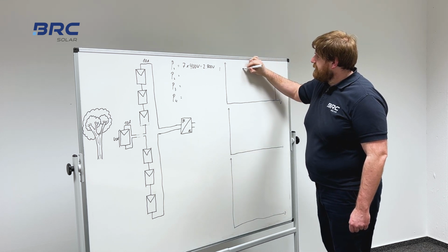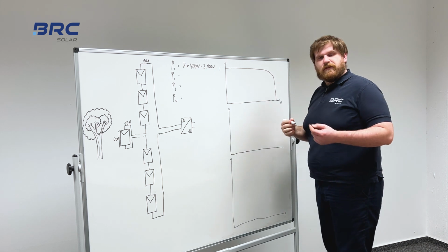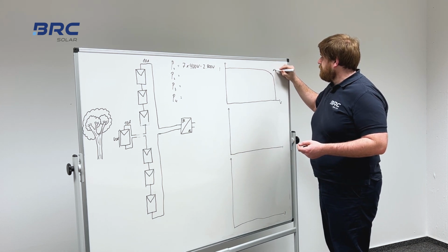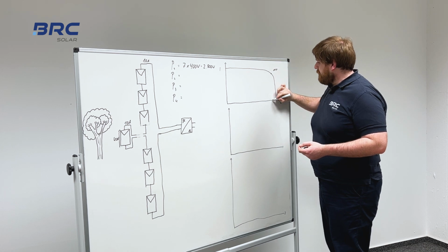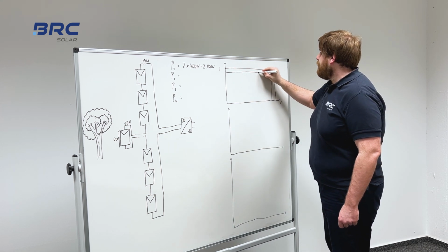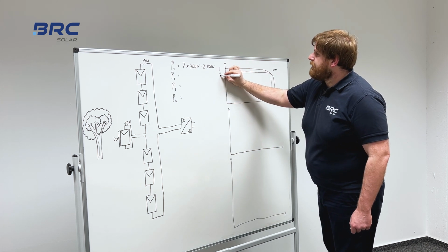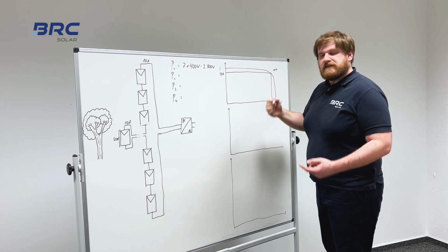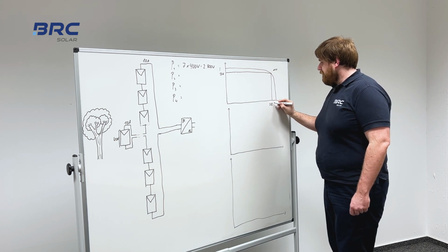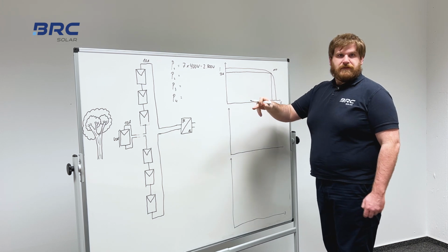And we will see that the best current and the best voltage in this scenario is right here at this maximum power point. And this is right on the situation where we have this 10 amps in the whole string, and also the voltage of the string of 280 volt, 40 volt each module.